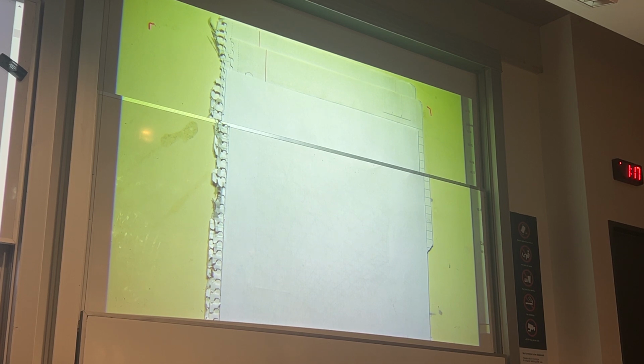So I'll point out one key thing: what you're meant to pick up is that we have vertical lines here, so we must have isentropic compression and isentropic expansion in both our compressor, turbines and pump. And then finally you have this last graph over here, which we don't need at the moment, but we will come back to that later.